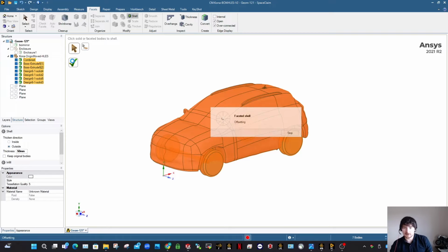It'll be a surface that will be created here. We're going to convert that surface into a solid body, like our other body of influences. This can sometimes take a while depending on the geometry you're using, so it can be temperamental. One thing to mention as well, the bigger you make this size, sometimes the more difficult it is for it to produce it. If you were to try a 500 mil version of this, it'd probably crash it. So keep things small, definitely at the very beginning, for the first shell.